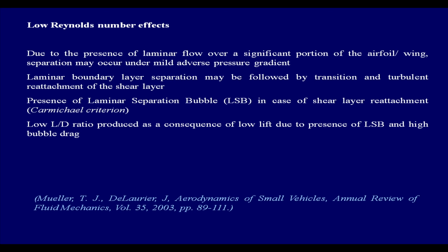There is enormous loss of lift, there is increase in drag, and therefore, the aerodynamic efficiency of the lifting surface massively gets affected. That is the L by D ratio we are talking about. L drops, D increases, and therefore, L by D, the ratio, is going to suffer very adversely, and the aerodynamic efficiency will be lost. So, if you are going to design configurations which are to operate at low Reynolds numbers, then you have to be aware of these issues, and you have to design it in such a manner that such problems are averted or tackled in real time in some manner.